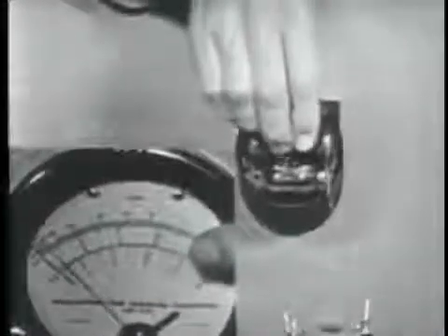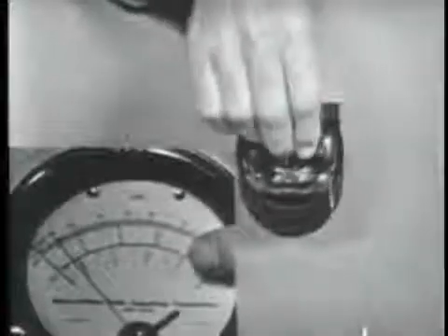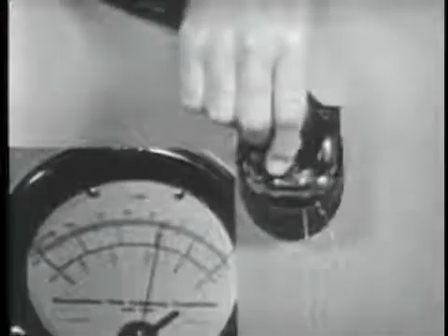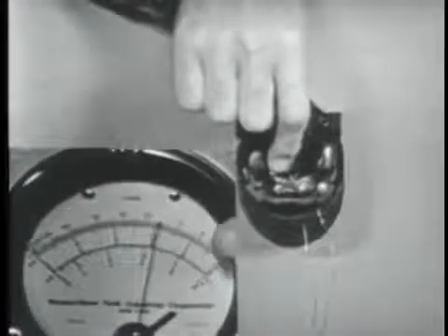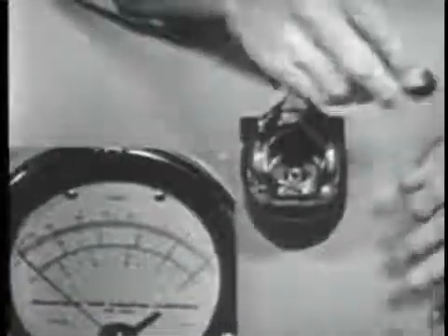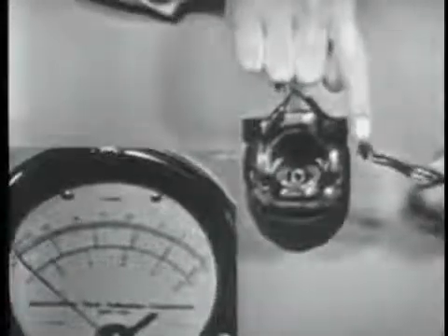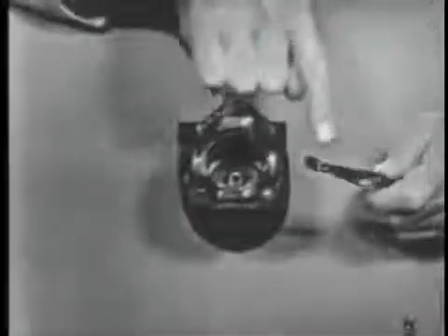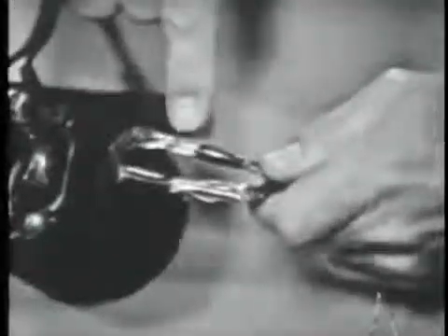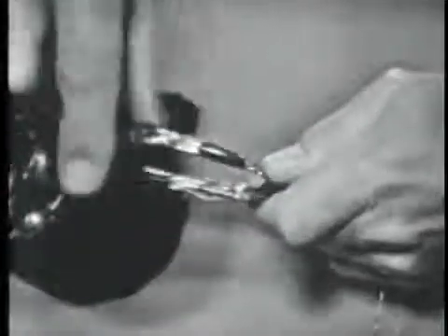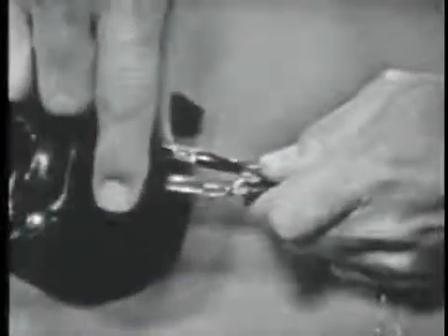And you can see as I take the loop out, it goes away, put the loop back in. I've got to get the loop all the way down in there. There you go. Now we have the rotating magnetic field inducing a voltage into the loop, which we're reading on the PSM6. Now the important thing to realize here is that once we get a current flow in this loop of wire, we have a magnetic field established about the loop. Now this means that we'll exhibit a north pole on one side and a south pole on the other. Or in other words, we have magnetized the loop. Made it an electromagnet, right?